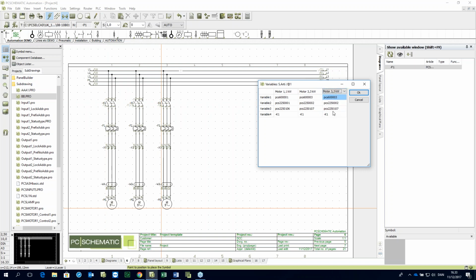All data in this drawing is changed because I have in the drawing created sets of data that fit with a component of a certain size. Because again, as we started saying when we started this, if I have a big motor, I'll have thick cables and big terminals and a big motor protection. If I have a small motor, it'll be thinner cables and smaller terminals and a smaller motor protection.